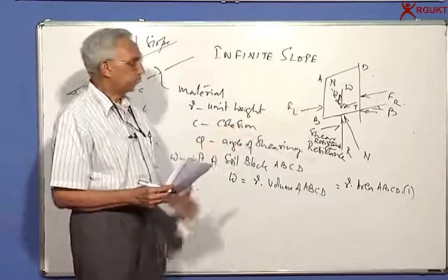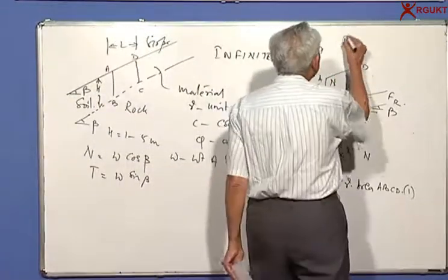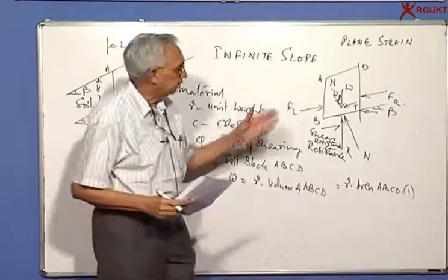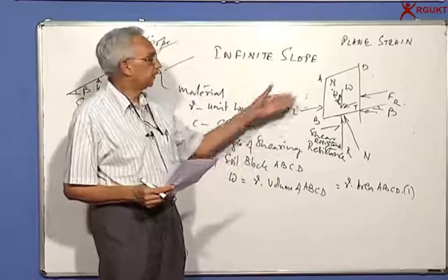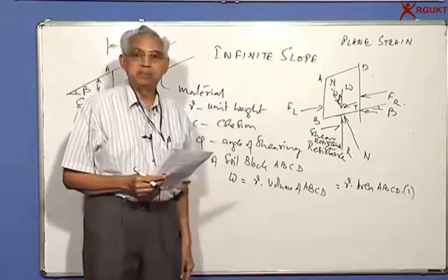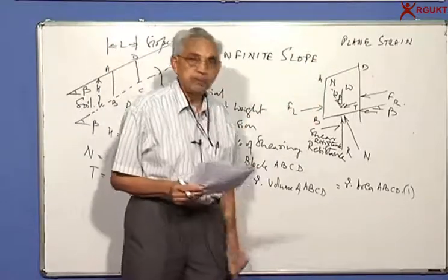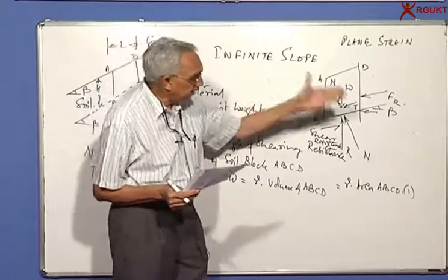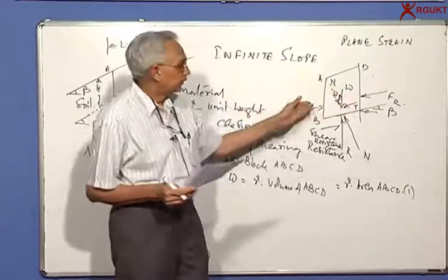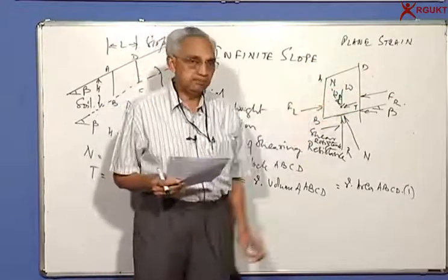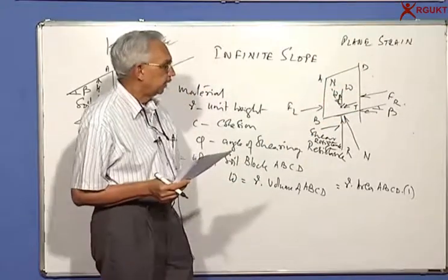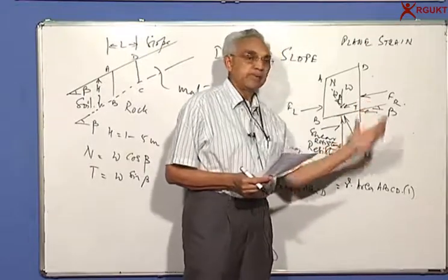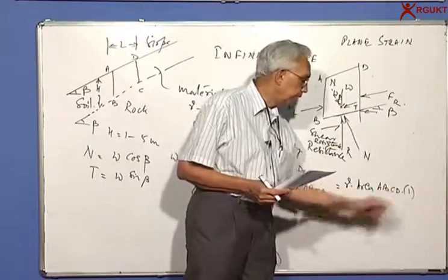All these problems are usually called plane strain problems. What it means is whatever strains, stresses, forces, they can be only within the plane perpendicular to the board. We are not interested in the deformations because the same soil is existing for maybe hundreds of meters on either side. So if I take a unit length perpendicular to the board, that will give me volume when multiplied by area.